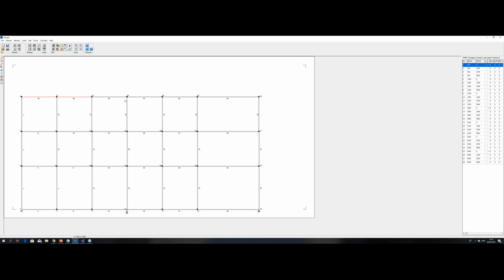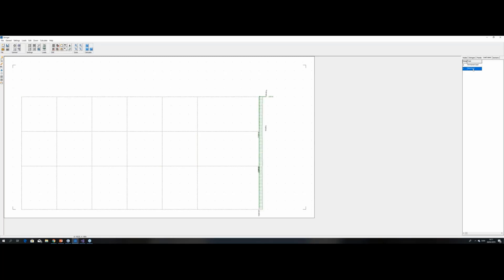We can also put loads on the stringer, but be aware, all the loads are moved to the nodes. So if we put in a load on this one here, all the loads are automatically moved to the nodes. We could put in 200 kilonewton per meter. Okay. We put also some load in here. And we can see the load here, permanent load and wind load.